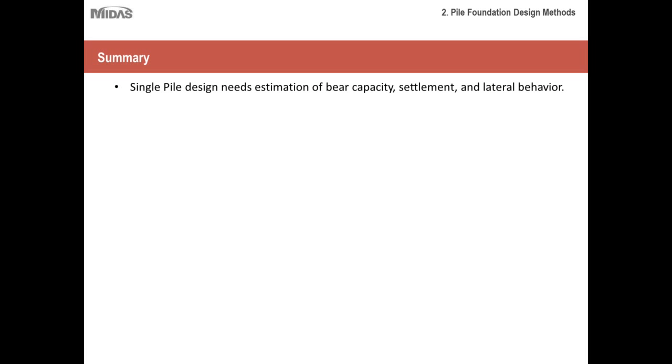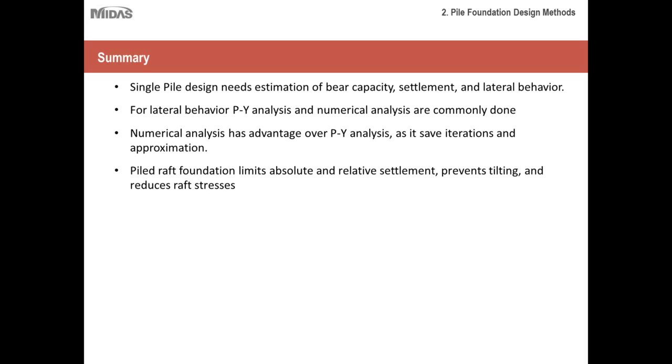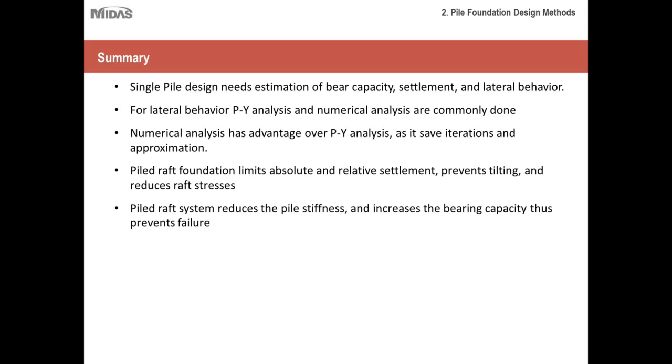Now let's move on to the summary of chapter 2. So the single pile design needs estimation of bearing capacity, settlement, and lateral behavior. For lateral behavior, PY analysis and numerical analysis are commonly used. Numerical analysis has certain advantages over PY analysis as it saves iterations and approximation. Pile raft foundation limits absolute and relative displacements or settlements. It also prevents tilting and reduces raft stresses.